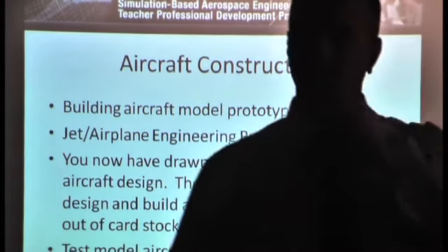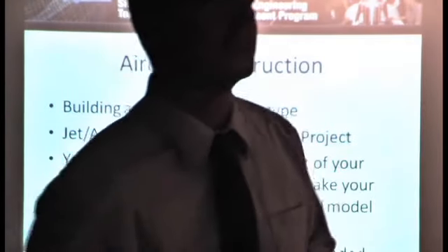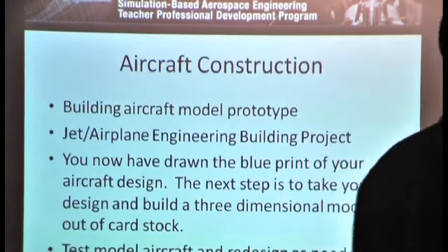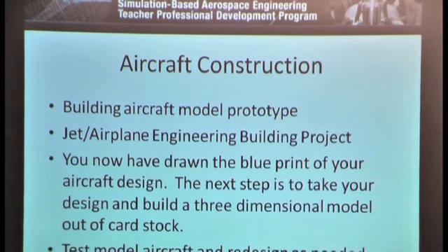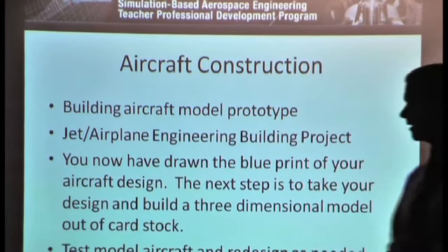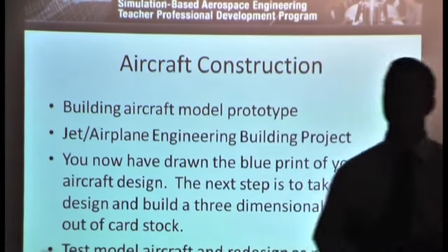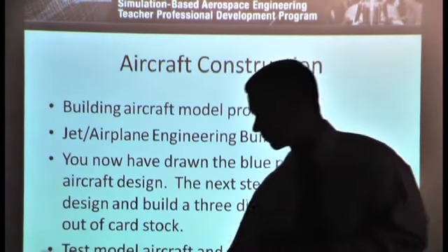What can we do to make it better? Should we add some more weight? Is it off balance? How do we change that? What can we do to make it fly straighter if that's what you're trying to achieve? If you wanted to curve it, what controls could you add? Could you add some elevators in the back to control the pitch? Could you add some ailerons somewhere along the side to control the roll? What can you do to change your aircraft design to improve it, and to constantly redesign it, refine it, test it, and then keep working with it?